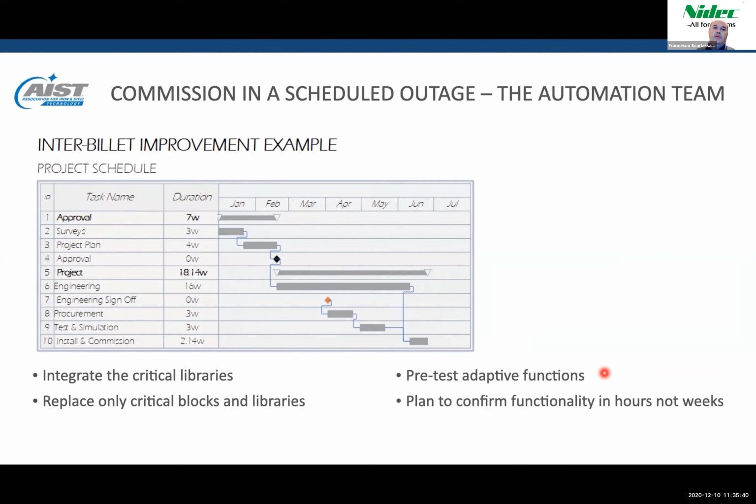During the commissioning, the team should enable one regulator at a time. For each regulator, test for a few billets or a few hours. Improving the conservative default setup, you can achieve better control and speed, a kind of fine tuning. So the regulator should have some default values that are pre-tested and able to achieve a good result in a short time. Of course, the process of achieving sweet spot operation can take days or weeks, depending on the result of the test. But this is important: the production will still match or exceed the historical production immediately, because you are deploying a well-tested system.